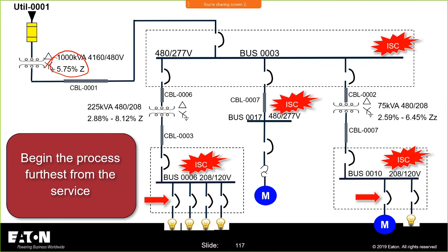You have to make guesses. What you'll do is go to the manufacturer that you're going to use. You have to do a basis of design. You're going to base your design on a specific manufacturer that makes your life easier, and you're going to pick the lowest, say a 1,000 kVA transformer. You're going to ask that manufacturer what's the lowest impedance for those transformers and put that in as a ballpark figure. These conductor lengths, you're going to estimate those at pretty short.